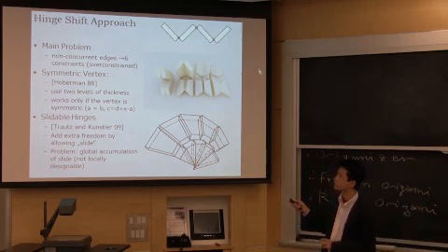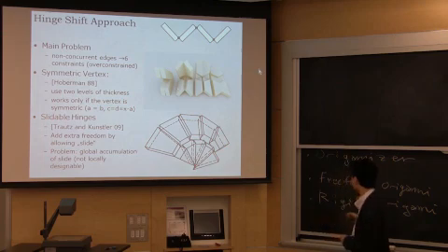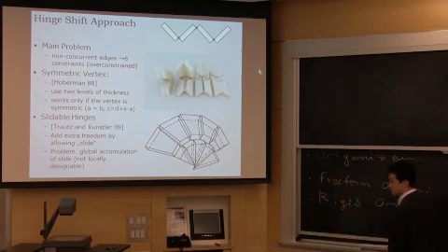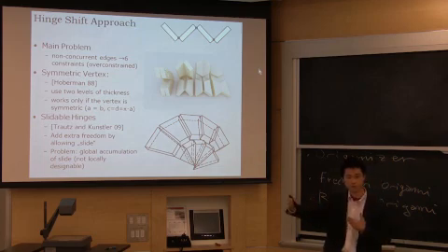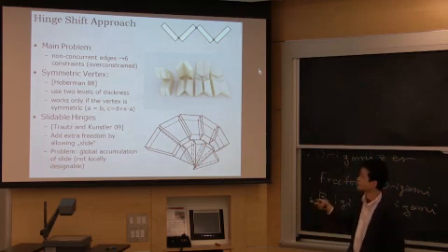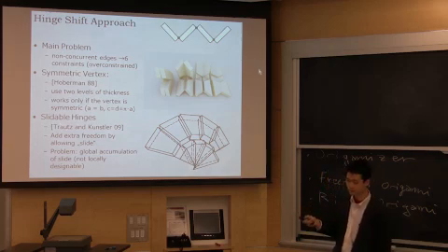But rigid origami mechanism assumes that the fold lines are concurrent, which means that it includes translation constraints, and it increases the number of constraints for each vertex. It was previously 3 constraints, but it becomes 6 constraints because it includes translation, which is very bad. But there is a symmetric vertex that allows that.